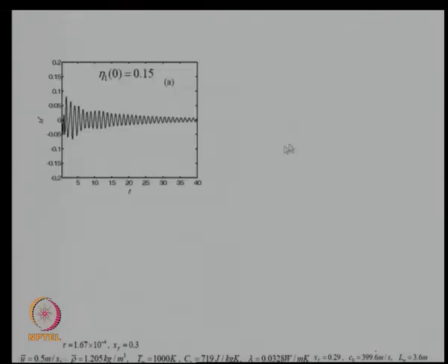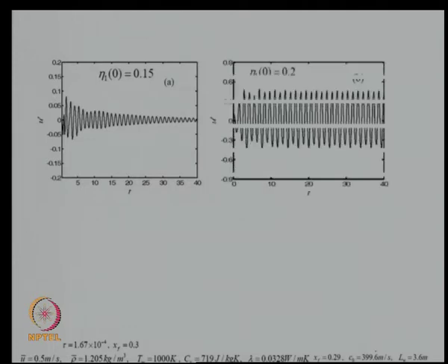So I have given the parameters at the bottom of the screen. You start with a small excitation and you see some kind of growth in velocity followed by decay. If you are in a subcritical zone and you snap your fingers near a Rijke tube, you can actually hear this. Now if you jack up the initial condition just a touch more, you actually get a different asymptotic state.